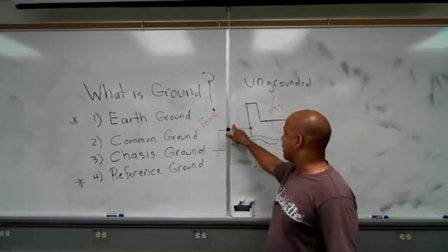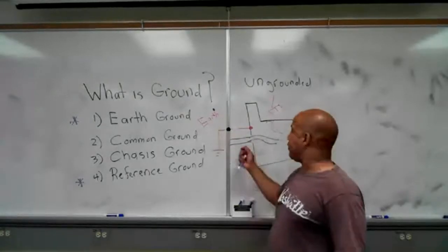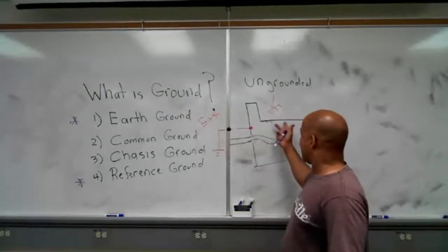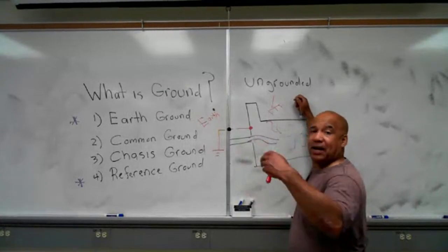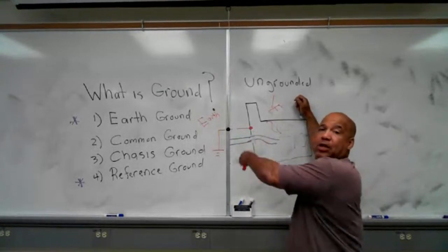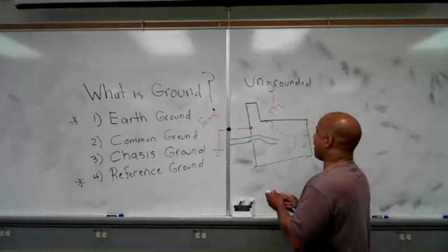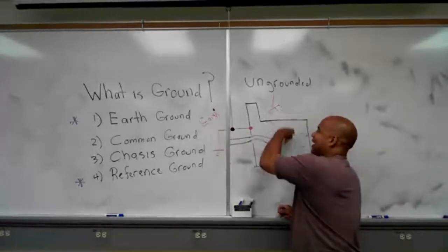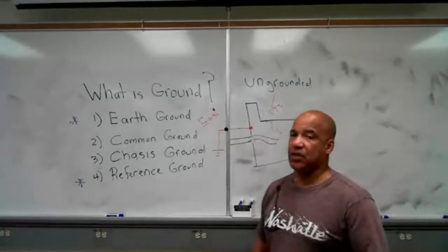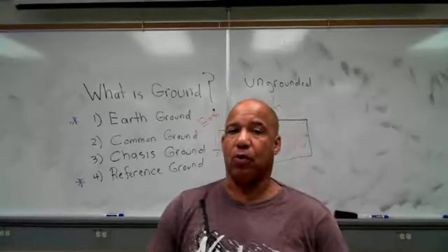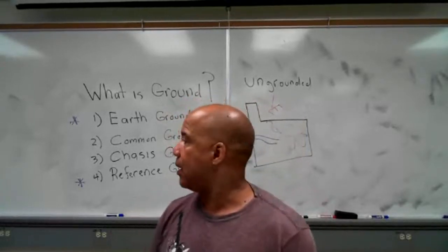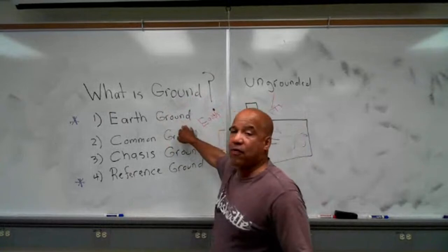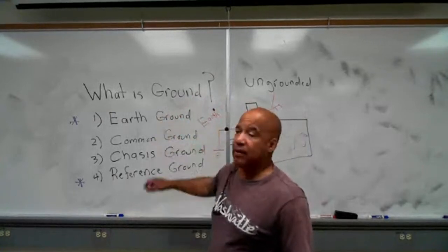If you were to break that ground wire, or you take it off, now this thing is no longer at ground potential. So when I touch against it, it's at a higher potential than I am, it's going to flow through me. But as long as I have it connected up, it forces that case to be at ground potential, and current has no reason to flow through me or a child that's touching the case of the machine. So to write down, earth ground is for safety.